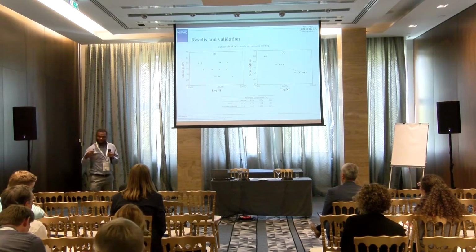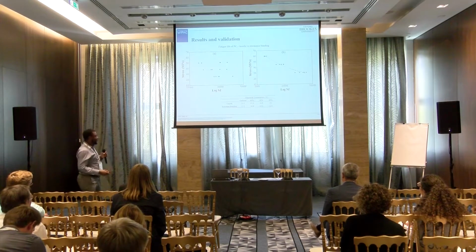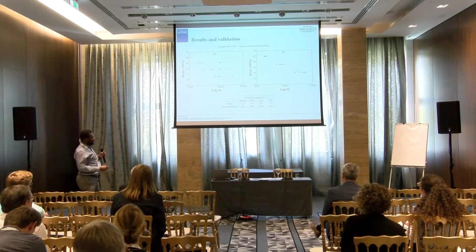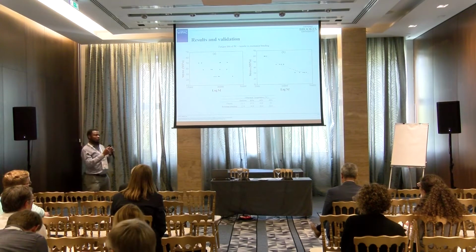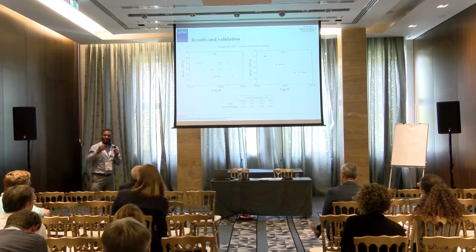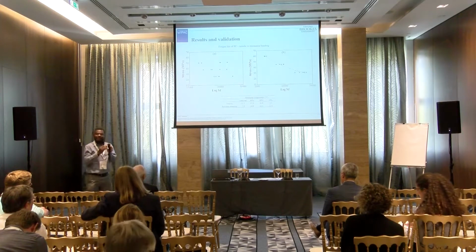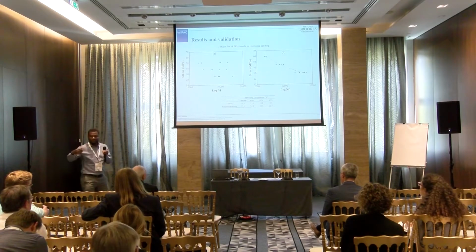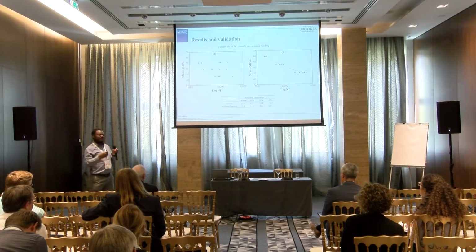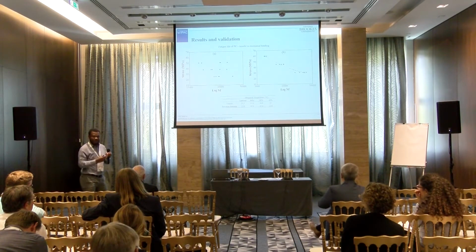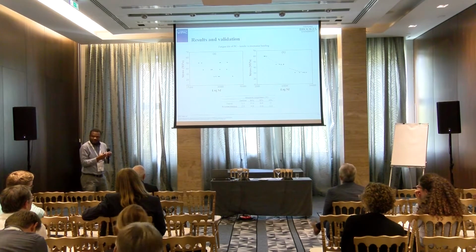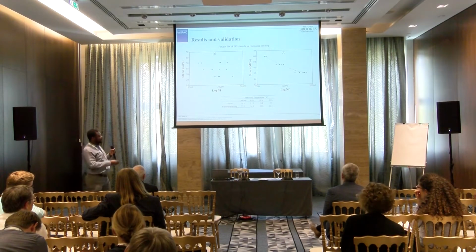And so what happens here, we think that at 80% it's going to 37.2, which softened the material. It made the material flexible, so it kept going, and then it went on to have a higher number of cycles, okay? Because of the temperature, it made it a little bit softer. But for resonant bending, something actually happened that was the opposite.